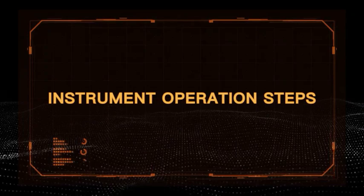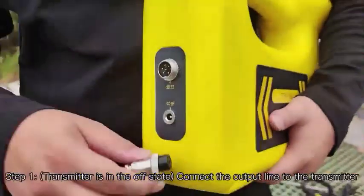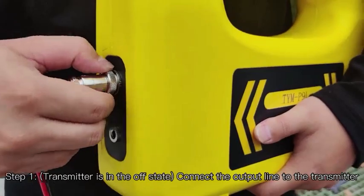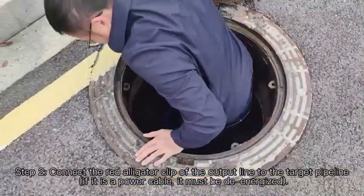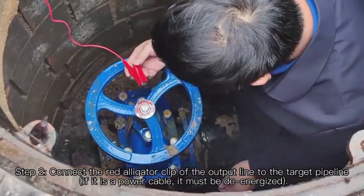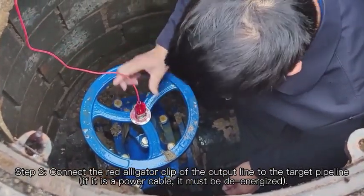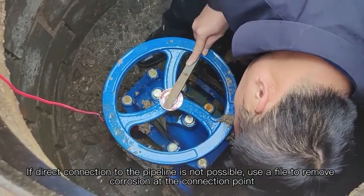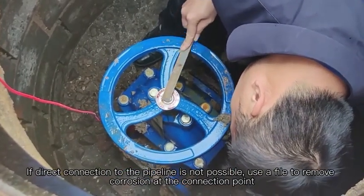Instrument operation steps. Step 1. Transmitter is in the off state. Connect the output line to the transmitter. Step 2. Connect the red alligator clip of the output line to the target pipeline. If it is a power cable, it must be de-energized. If direct connection to the pipeline is not possible, use a file to remove corrosion at the connection point.